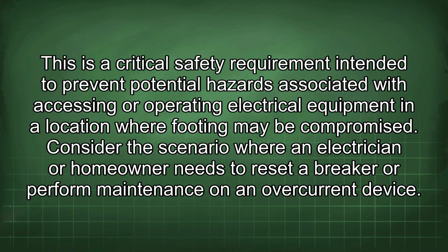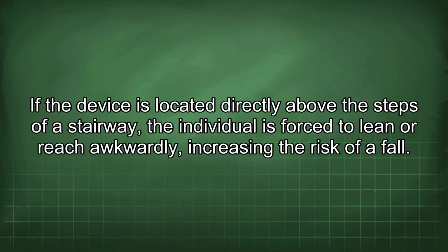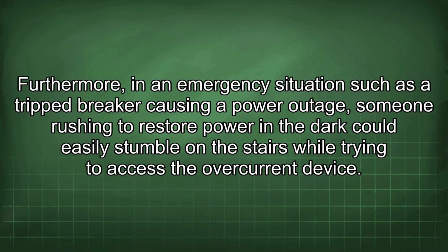Consider the scenario where an electrician or homeowner needs to reset a breaker or perform maintenance on an overcurrent device. If the device is located directly above the steps of a stairway, the individual is forced to lean or reach awkwardly, increasing the risk of a fall. Furthermore, in an emergency situation such as a tripped breaker causing a power outage, someone rushing to restore power in the dark could easily stumble on the stairs while trying to access the overcurrent device.